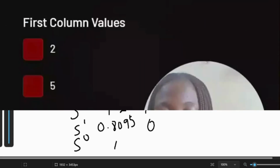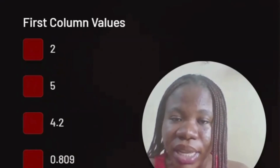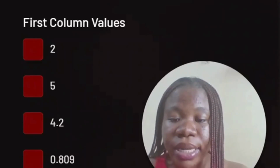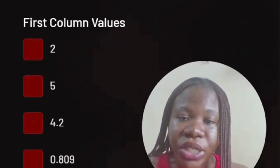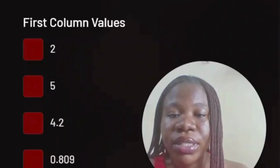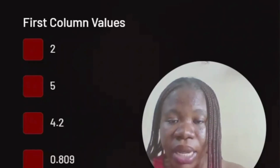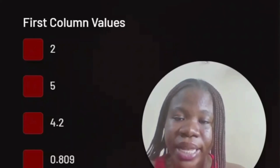So in this section, we are going to really answer our question: is our system stable or not? To do that, we need to remember that we need to look out for sign changes first of all. Why do we need to look out for sign changes? The Routh-Hurwitz criterion tells us that the number of sign changes within the first column of values directly corresponds to the number of poles in the right half of the S-plane.